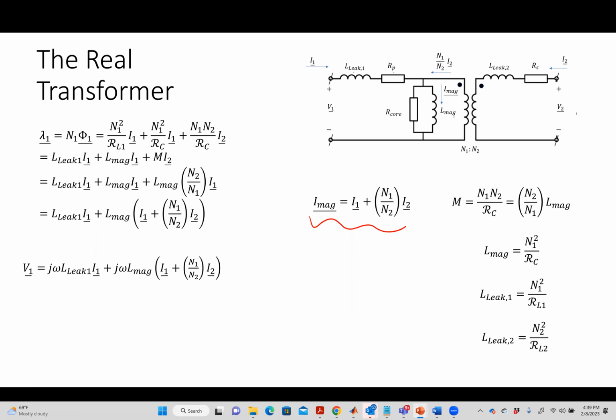We throw in the core resistance and we throw in the winding resistance. Everybody gets all tied up in knots about those things, but we're talking about very small resistances. If I measure that resistance at low load versus high load, heating is going to happen and those resistances are going to change. We don't tend to worry too much about those numbers. Basic idea is that we understand what this model is.